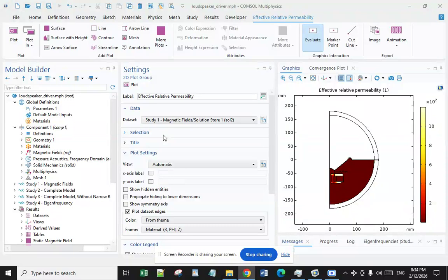The magnetostriction effect has been used to generate both SH-type and Lamb-type waves in steel products. Recently, due to a stronger magnetostriction effect in nickel than steel, magnetostriction sensors using nickel patches have been developed for the non-destructive testing of steel products.